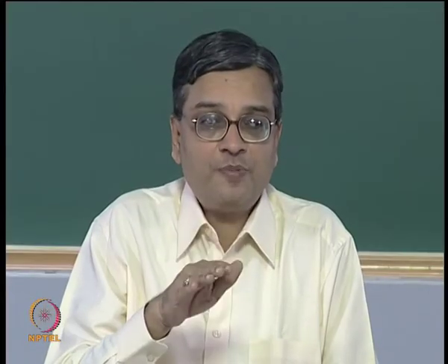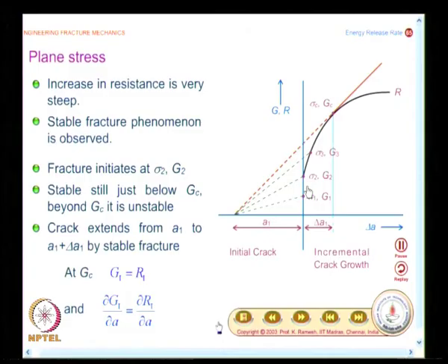If the load is stopped, the crack also will stop. But once you come to this position, even a very small perturbation will make the crack propagate catastrophically. So, what you will have to really look at is a stable fracture followed by unstable fracture, and this is where I said when you are doing a plane stress test, you do not need to introduce a sharp crack like what you do in a plane strain fracture toughness testing.